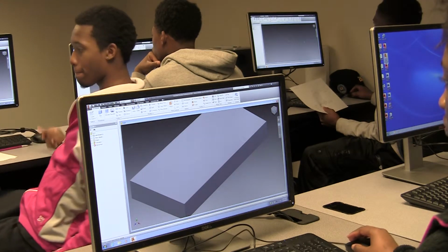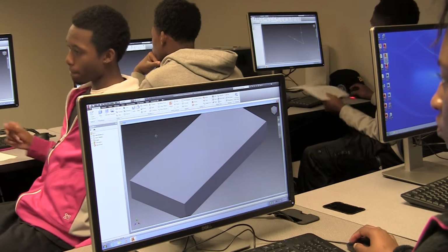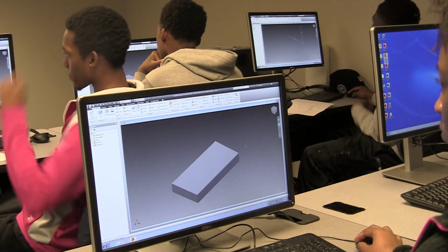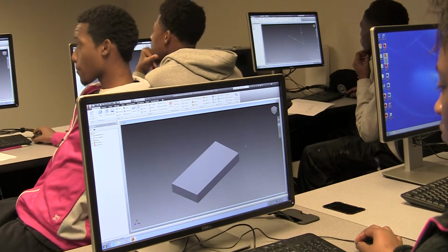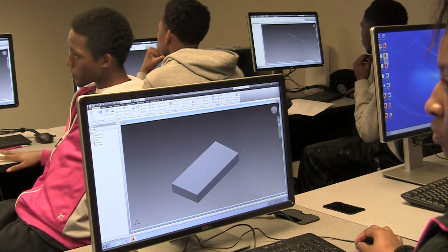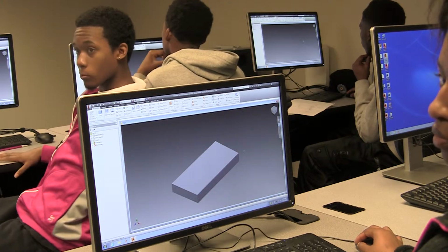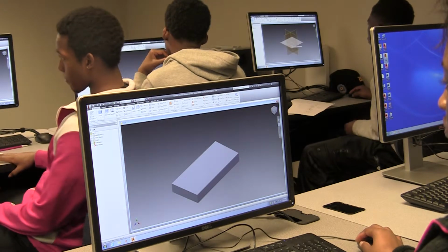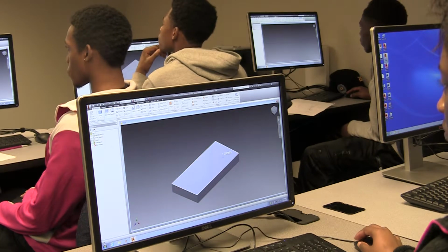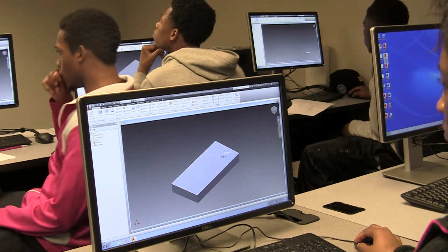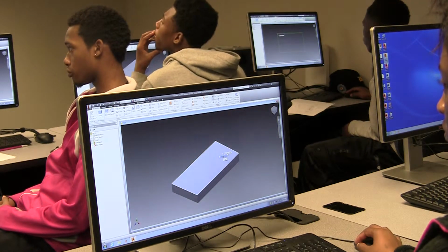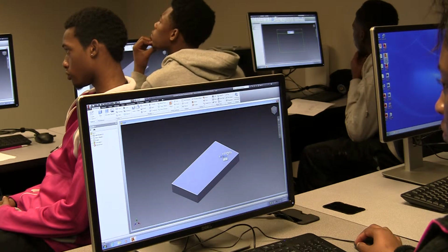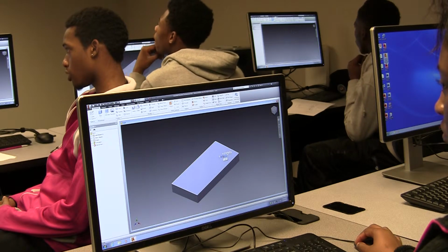Now, after you get an initial solid block, this part of the design process you can start to make your chassis from. So if you're going to have a long, narrow chassis, you'd start with something like this and you're putting it into CAD in your design process. You'll eventually start a new sketch, but your new sketches can only be made from flat surfaces. In most cases, there are parts of your robot that you may want to be rounded off, but you cannot draw on a rounded surface with this software. Well, you can, but that's a long story and I'm not going to confuse you right now.